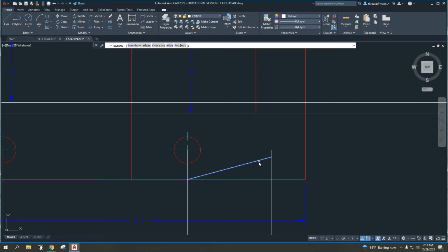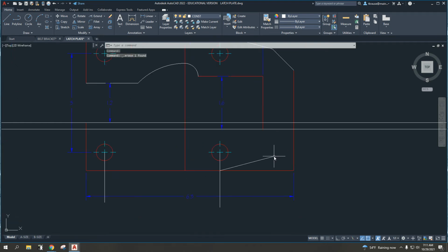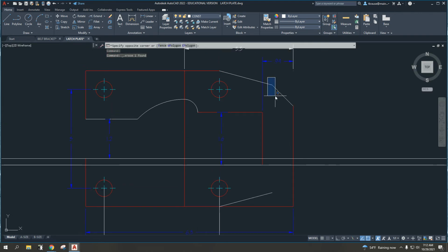You see there, it's giving me in the preview where I want to extend that line to meet that other line. I can do that over here, I can do that here. I can use this extend command in multiple places, but I just want to extend it to meet that line. So I'm going to left click on my mouse and hit enter or escape when I'm done. And now I have created the endpoint of that line, which is right up in here.